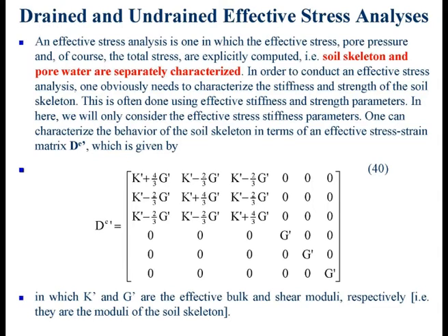Should I use the undrained modulus with nu u equals 0.499, or as Plaxis would have loved it, should I use effective stress analysis, E dash, nu dash, and so on and so forth? You know what I mean? So you get this kind of question: but I'm doing undrained analysis, why can't I use E u and nu u equals 0.49? So basically, E u and nu u equals 0.49 is actually a total stress analysis. It is actually total stress analysis.